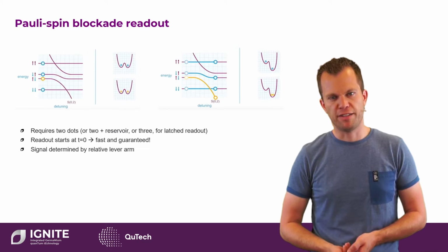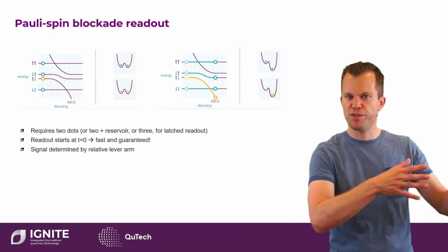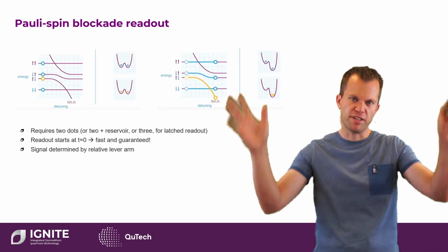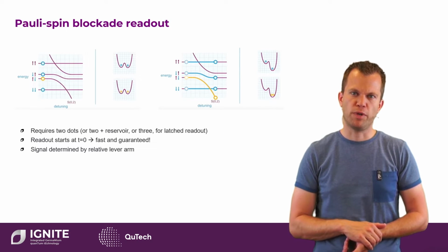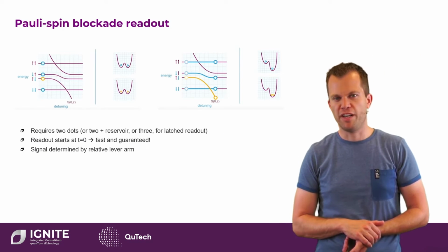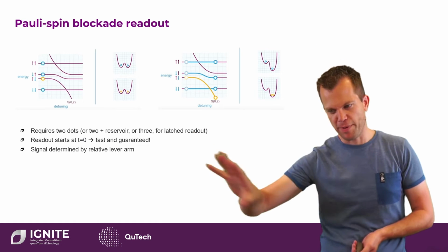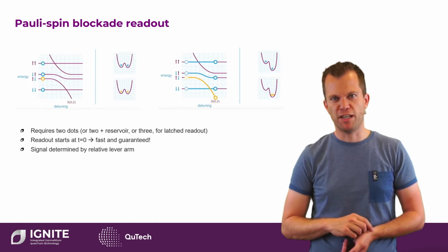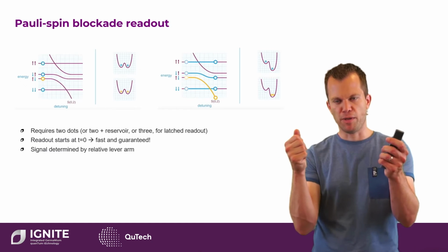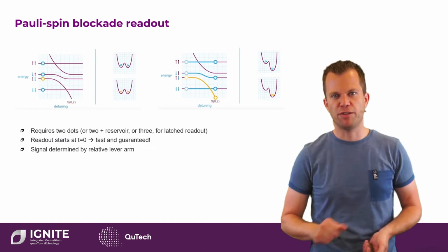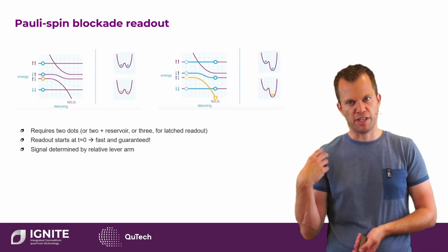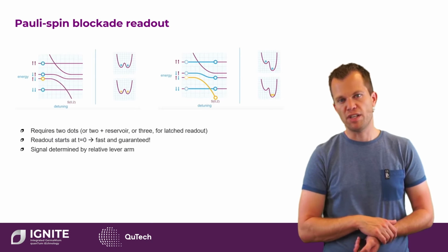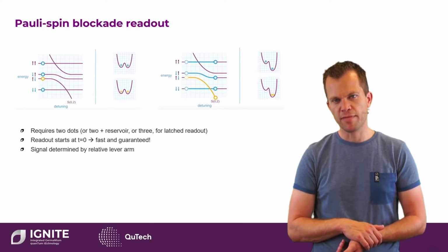Perhaps a more appealing manner is actually to reuse a nearby quantum dot. So if we have this picture again of a two-dimensional array of quantum dots, one may imagine that one is implementing a certain algorithm, qubit operations. In the end, we want to do a readout. Well, okay, then we can maybe use another quantum dot to read out the state, such that, let's say, every quantum dot used for measurement requires another ancilla for readout.